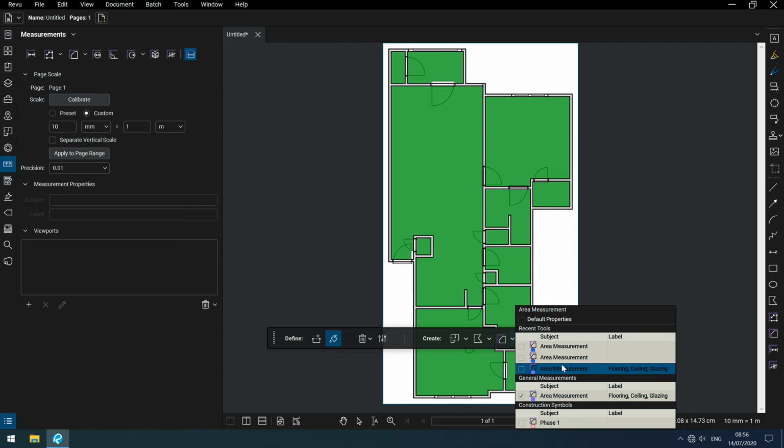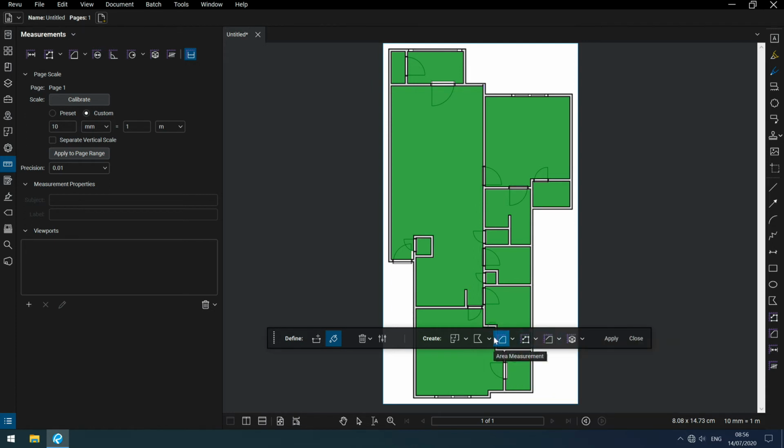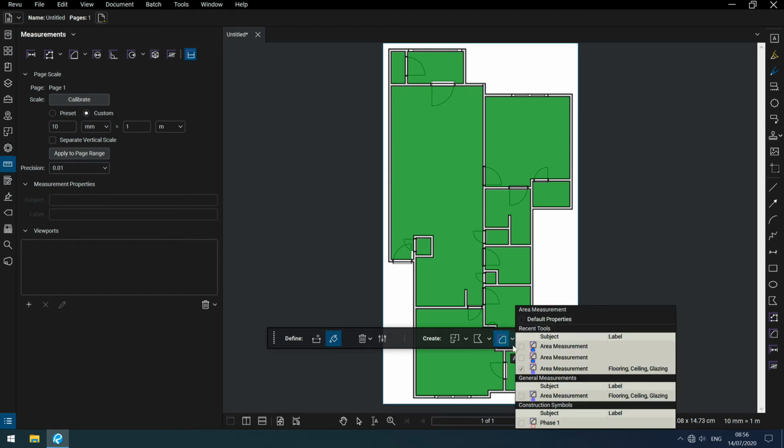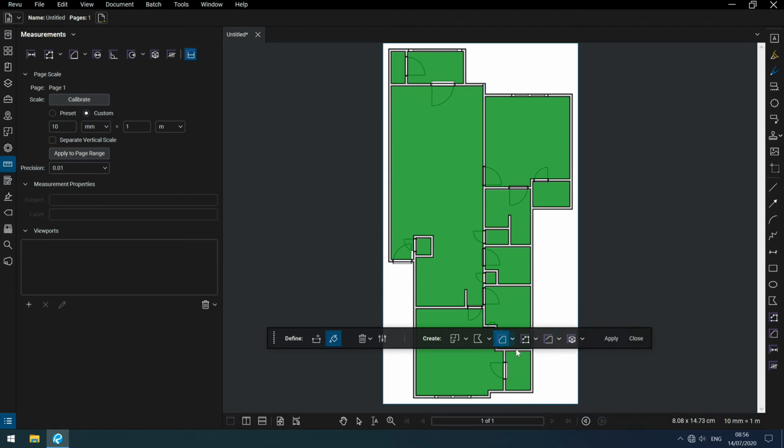We haven't talked about the tool chest today. That's probably going to be covered in one of our future presentations. For now, just know that you can select pre-prepared measurement settings here and select which kind of measurement you want to take. You're not restricted to one kind of measurement, so if I wanted, I can click on the poly length measurement or the perimeter measurement as well and take more than one measurement with this dynamic fill tool at the same time. For our presentation here, I'm just going to restrict it to the area measurement.